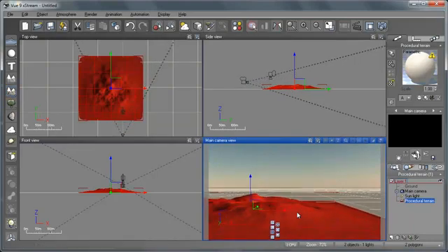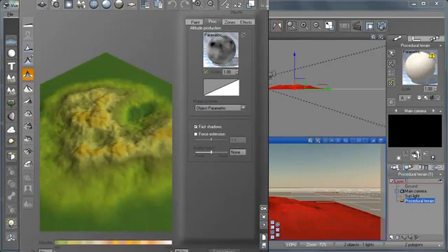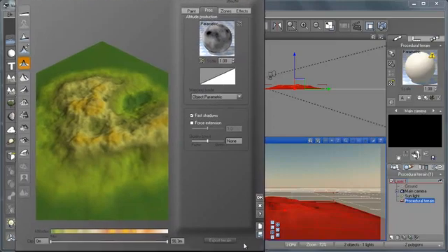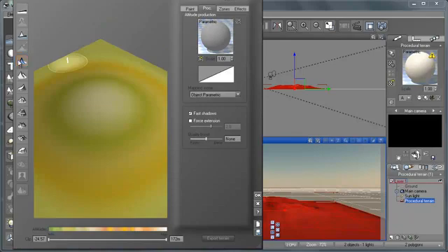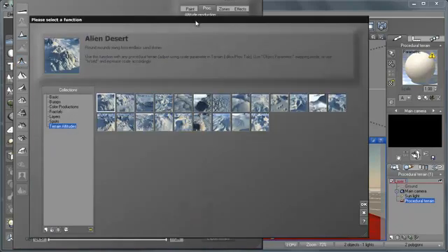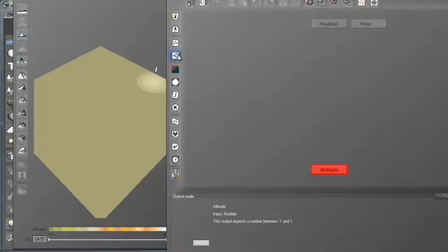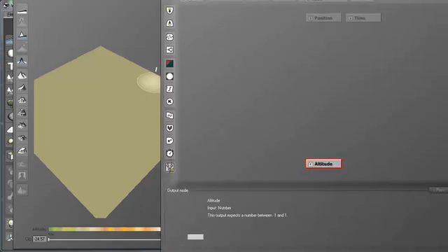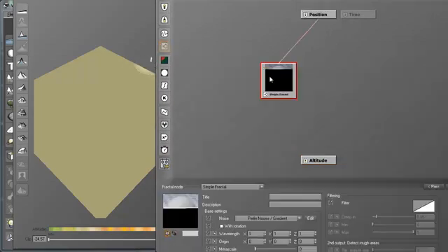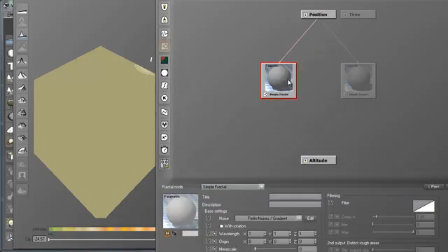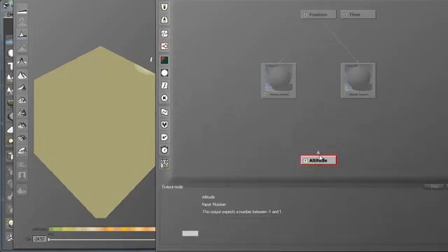I'm going to double click on this terrain, and as usual I'm going to reset the function, uncheck the zero edges, and right click, edit function. Here we are in the function editor, and we're going to do some manipulation there. I'm going to create two fractal nodes here, pick the altitude map and connect it to one of the two fractal nodes I've created, and choose altitude.